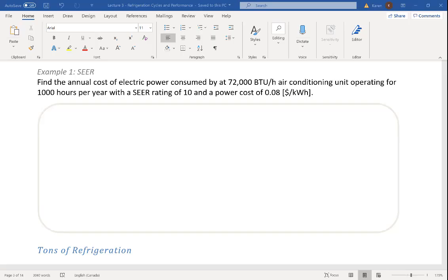They are not a math equation per se. They are rating systems that are defined and invented literally to have imperial units of BTUs on top and energy, watt or kilowatt hours, on the bottom. The more you look into SEER and EER, you'll notice that sometimes it's called BTU per hour on the top and watts on the bottom.